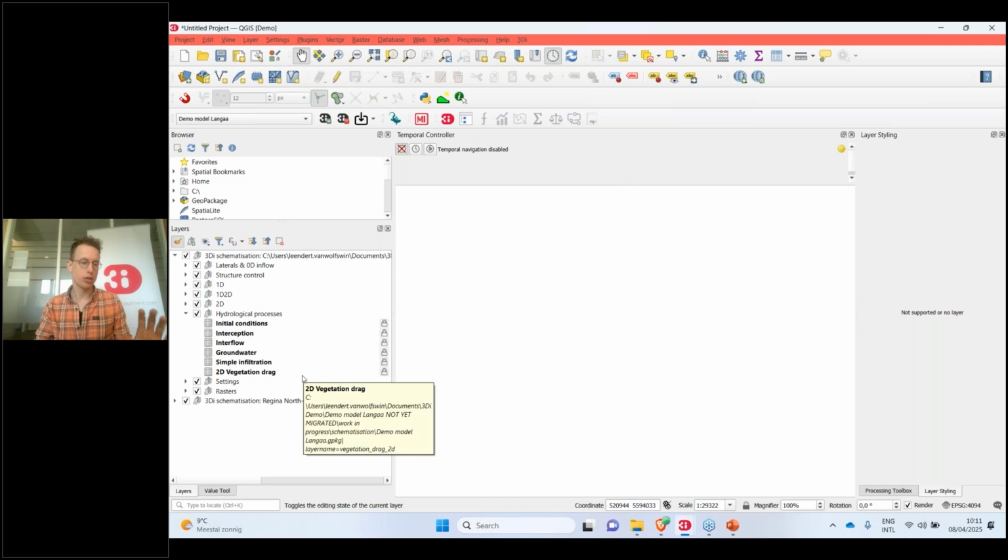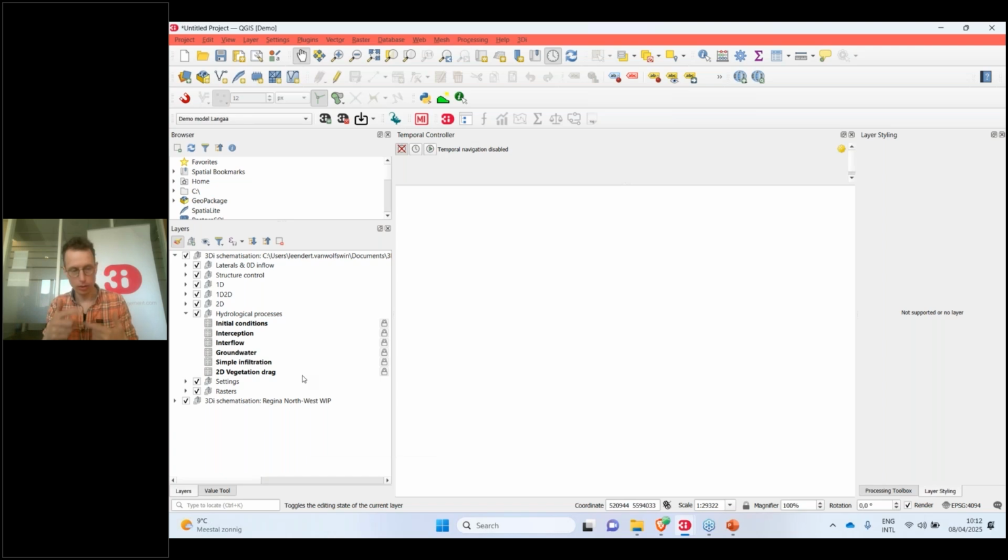Some of these settings are needed when creating a 3Di model, and some of them are used only in the simulation template. In the 3Di documentation, you can find exactly which tables are in which category, so that you know, if you want to do a lot of simulations with different settings, do I need to create a new 3Di model all the time, or can I simply change the settings when starting a simulation?